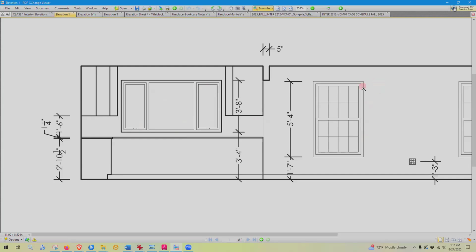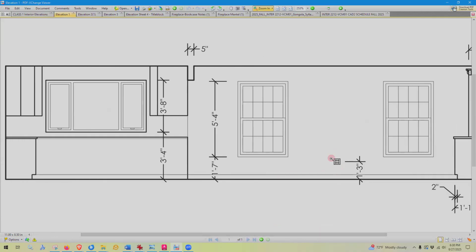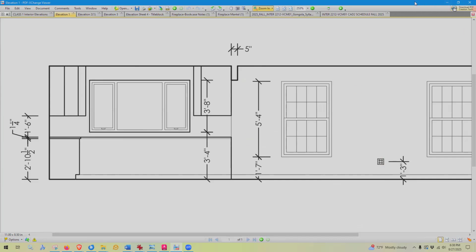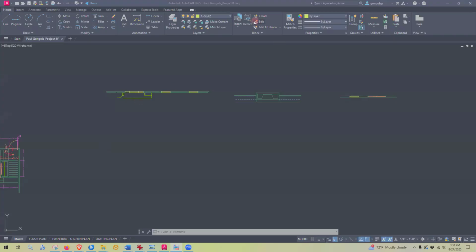So what we'll do when we draw these windows is we'll make the perimeter line here a little bit heavier and we'll keep all of this light. And then the most light stuff is going to be like this baseboard here. It's literally attached to the wall. I think I'm going to make this also light as well. So we want to be cognizant of line weights as we're drawing our stuff. So let's look at our layers and see what we've got here.